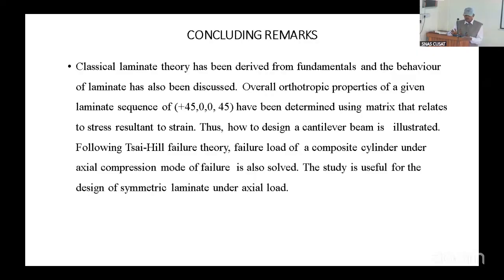And once you know these things, people can ask, what question will they ask? Can you give a typical unidirectional laminate property of a fiber, say carbon fiber? So you can say 140, remember 140 GPa, 7 GPa for ET, and the other thing also 6 GPa. Instead of 6, you can put 7 also. So compared to 147 and 6, it doesn't have much difference. So you say what is the value? Shear modulus is how much?